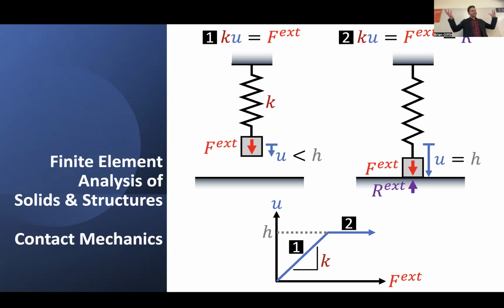And we'll then, if we have time, dive into some of the extensions of these same ideas into the domain of two-dimensional and three-dimensional finite element analyses, and how we can generalize similar descriptions of these constraints into that format of considering not just, let's say, a one-dimensional block coming into contact with a rigid surface, but rather what happens if I have two elastic bodies coming into contact? How do I define similar descriptions of contact constraints?